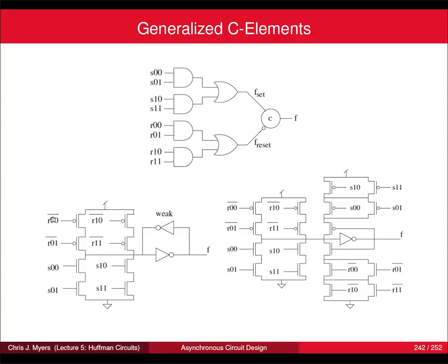And the complements of these two signals, they get complemented because in PMOS you've got a complementation. So if these are both off, that pulls this high, which pulls the output low. Or if these are both off, then that pulls that high. And then if none of these stacks are switched on, then you have this little weak feedback here that restores the state and keeps it at its stable value.